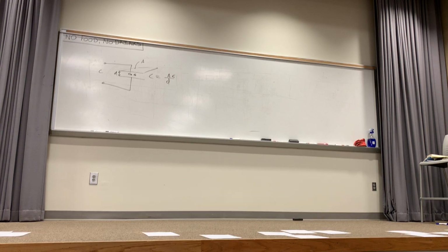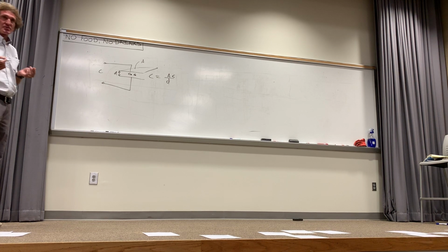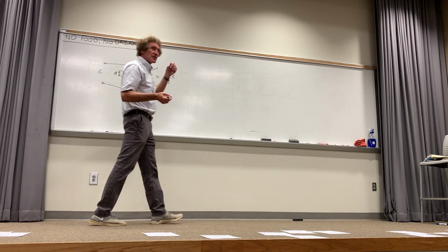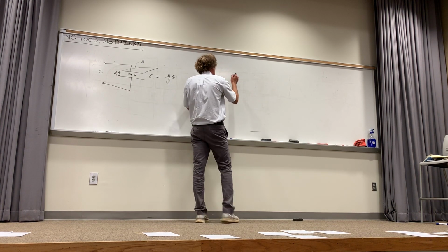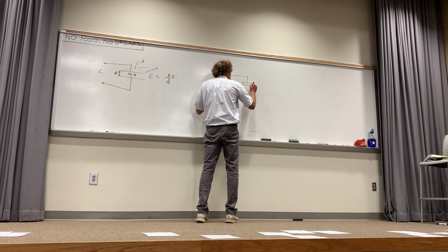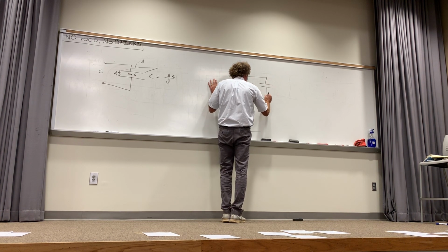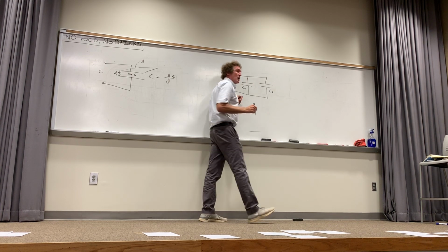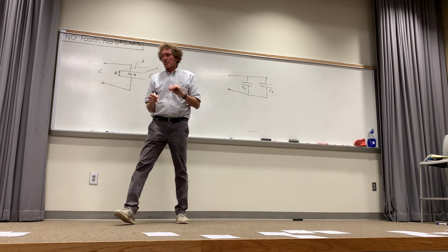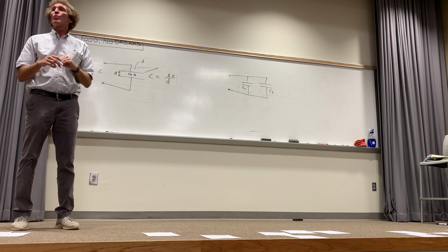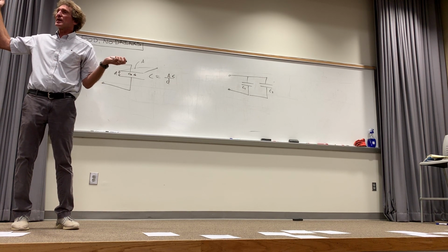Now, a capacitor is an energy storage device. That's fundamentally what it is. You charge it up, it'll discharge. That's it. Now, if you look at this formula and you think about how you add capacitors in parallel, I want you to think about this. I have some C1 here, and I have some C2 here. What happens there? Doesn't it look like the plates of the capacitor have got more area on them, not the separation distance? How many see that? Assume that they're both identical for now.